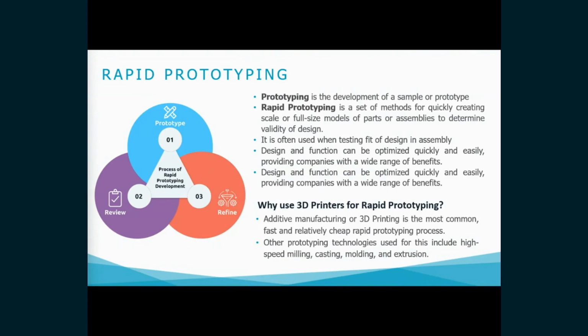Rapid tooling refers to the rapid production of tools using the same process that is used in rapid prototyping. Rapid manufacturing is used to create functioning end products. Rapid prototyping is particularly interesting for the production of smaller quantities or individualized products. Rapid prototyping, or rapid tooling, is aimed at producing an end product of high fidelity.